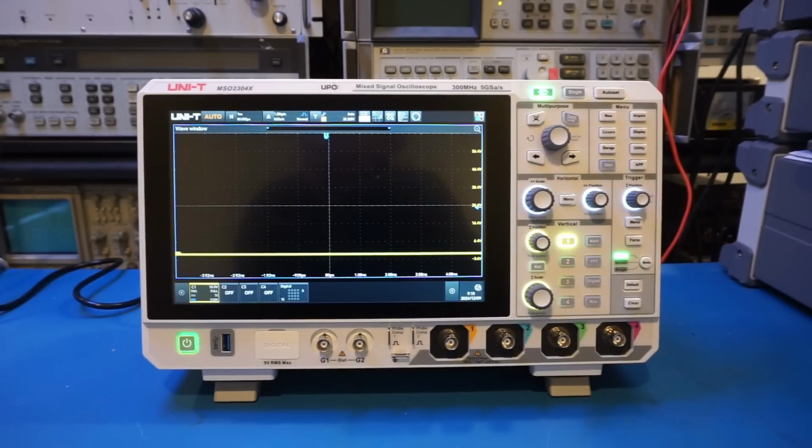In the specifications, it mentioned that the waveform capture rate is up to 500,000 waveforms per second, and in sequential mode is even higher, up to 2 million waveforms per second. Keep in mind that the trigger rate is not the same as the update rate, but they are related. Of course, the triggering rate is also dependent on many other factors, and the memory depth and the display method also affect the triggering rate. So let's actually take a closer look.